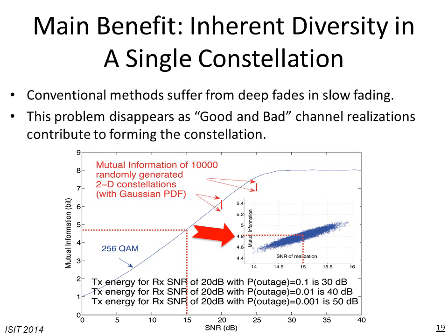So as you see, for the 10,000 constellation realizations, we have a spread of different mutual information. The x-axis for the case of media-based modulation, which are those random constellations, corresponds to the receive SNR, because sometimes we may get a constellation for which the average energy is higher than 1, or the average energy may be lower than 1. Consequently, for different realizations, we have different mutual informations and also different receive SNRs.